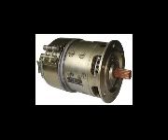The rotation of generators is termed either clockwise or counterclockwise, as viewed from the driven end. Usually, the direction of rotation is stamped on the data plate. If no direction is stamped on the plate, the rotation may be marked by an arrow on the cover plate of the brush housing. It is important that a generator with the correct direction of rotation be used, otherwise the voltage will be reversed.